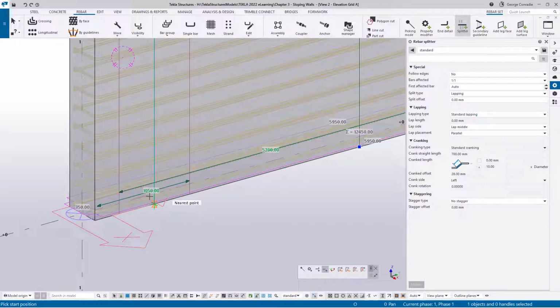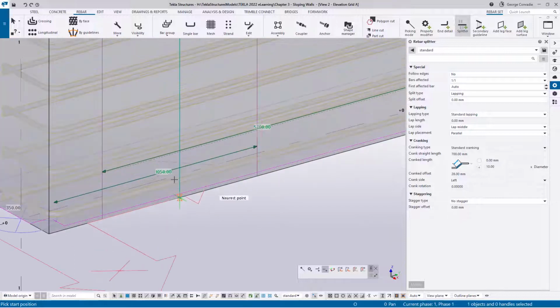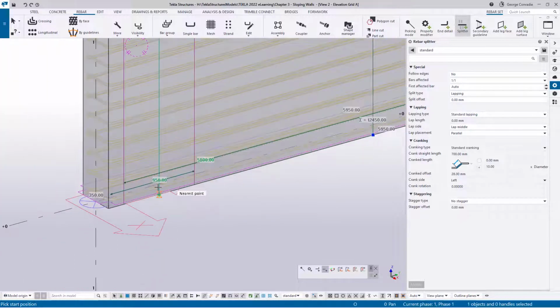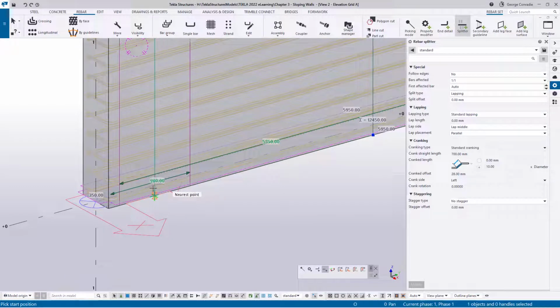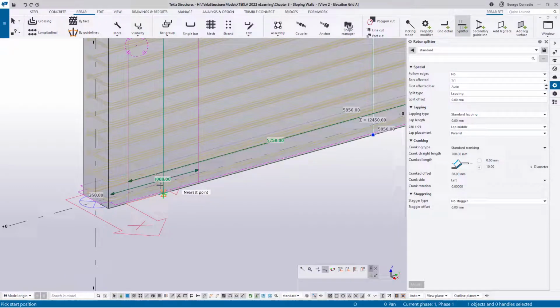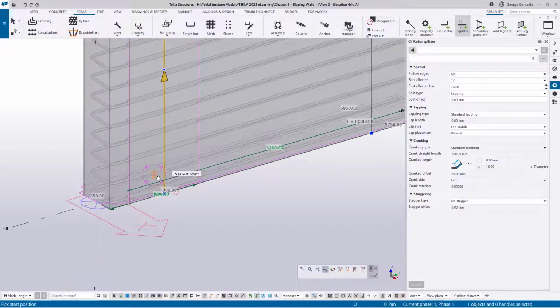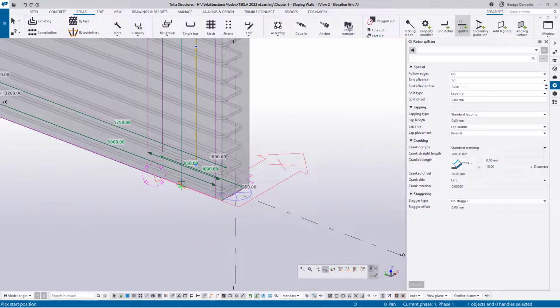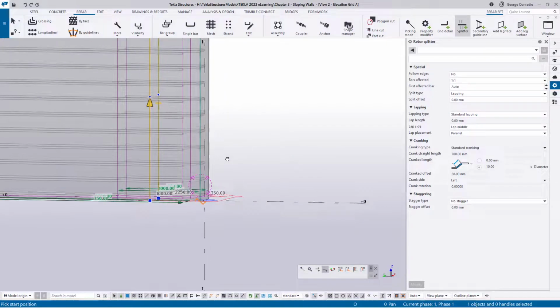You can see that arrow with the 1050 there is just short of the concrete, so it means that measurement's on the leg. The other thing I just quickly want to show is if you hover around here and you get really funny dimensions, what you could do is you could just hold in your shift key while you're hovering, and that will break it up into more manageable pieces. So we'll select the 1000, so it breaks the bar on that side. And on the other side, again, we can just pick our 1000. That breaks it. So we've got a U on this side.